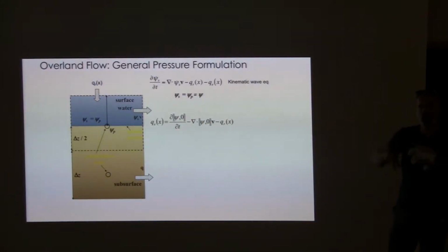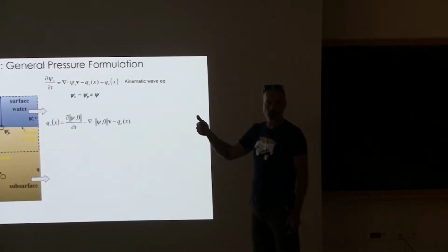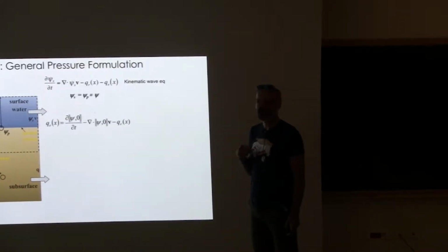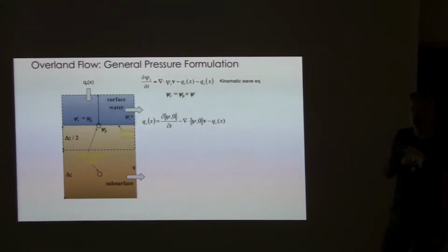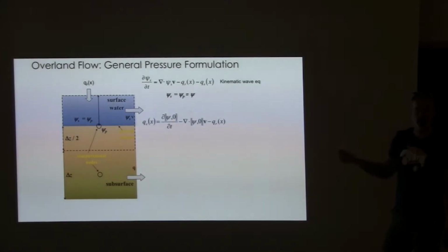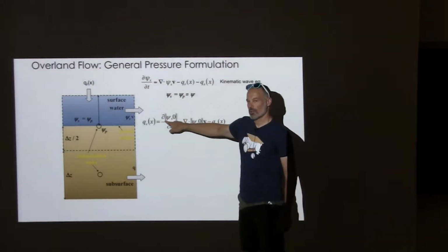So these two vertical lines mean the greater of psi, our pressure, or 0. And so what happens, again, jot this down in your little notepad. Think about what happens when psi is less than 0. We're in suction. We should be unsaturated.